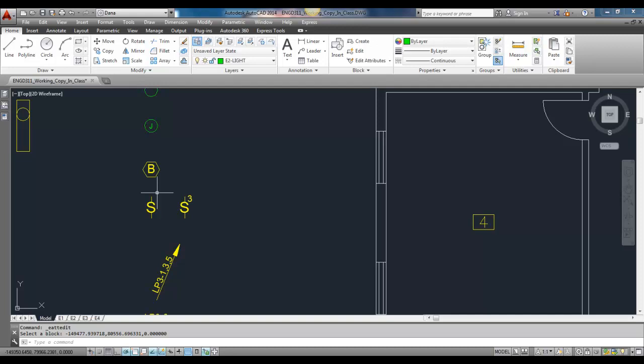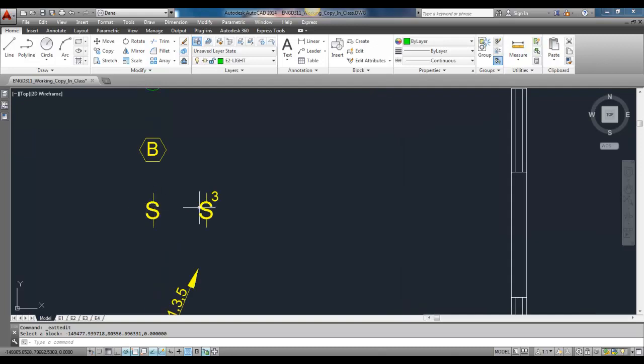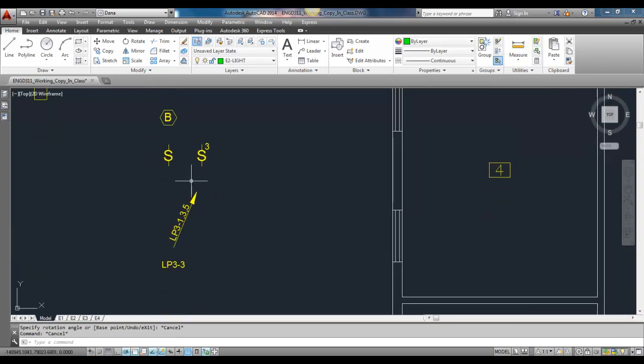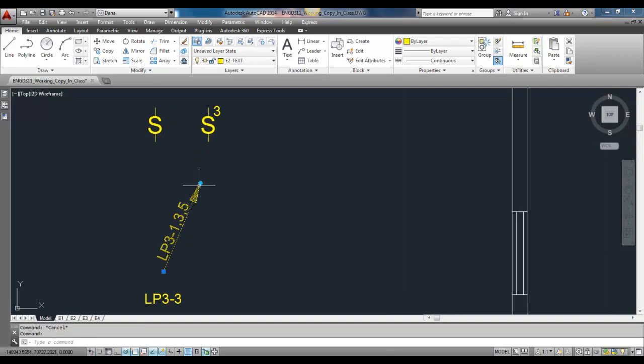So the other thing I've got here is a single pole switch, and a three-way switch. And again, I've got that same rotation configuration for these as well. So depending on which wall I'm putting it on and which orientation I need for those switches, I've got it configured so that I can just quickly change it. I also have a home run here, and the home run as well is connected, so I can point that towards the panel, from whatever junction box I'm going to be connecting that from.